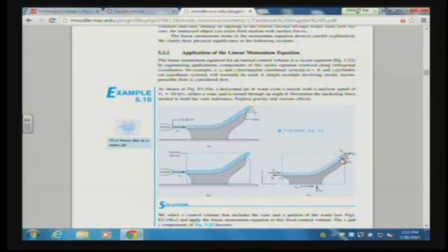So the component of momentum up here is going to have to be offset by a force term of analogous dimensions in the y direction. And if the momentum component in the x direction here is not completely offset by the x component here, then we're going to have a movement of the vane in the x direction.